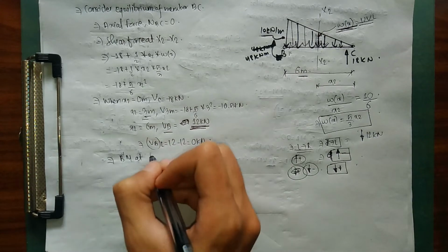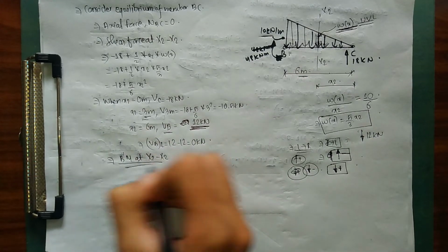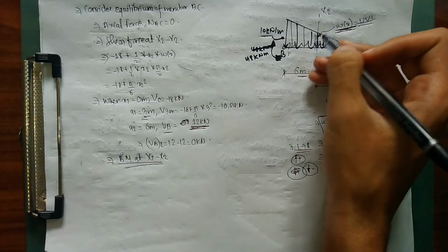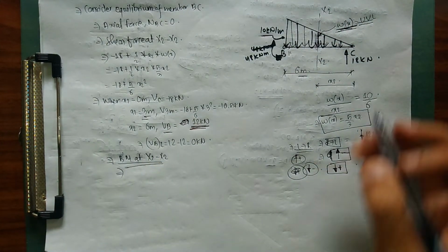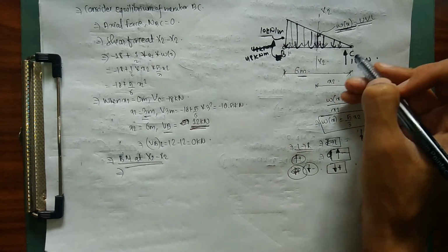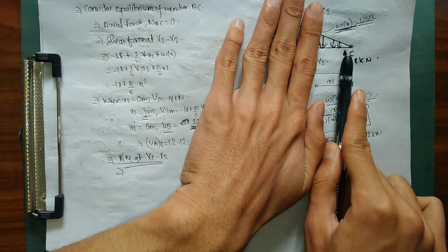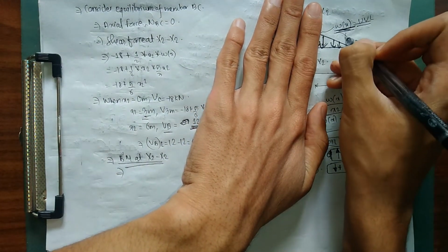So now, in order to calculate our bending moment, we are going to take our shortened section x2. We are going to take our bending moment over x2, and let me write down my general equation in this case as well. So right now I have my 18 kN at x2, and with reference to x2 it is acting vertically upward, and it's producing anti-clockwise moment.